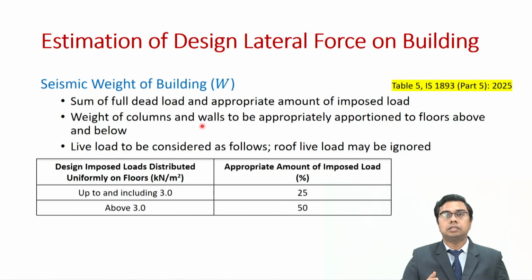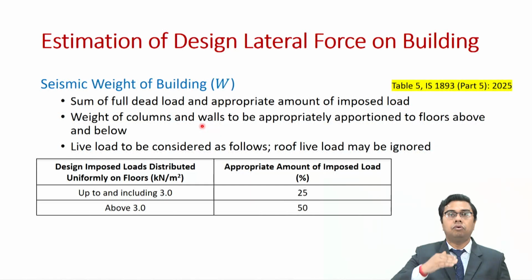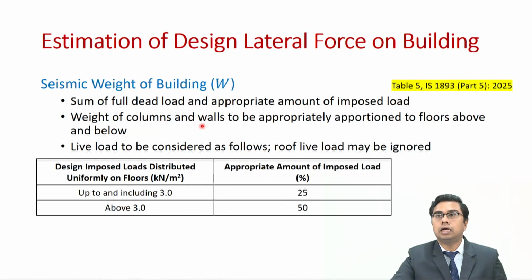While estimating the seismic weight of the building, the weight of columns and walls has to be appropriately apportioned to floors above and below it. The roof live load may be ignored. Okay, more details are available.